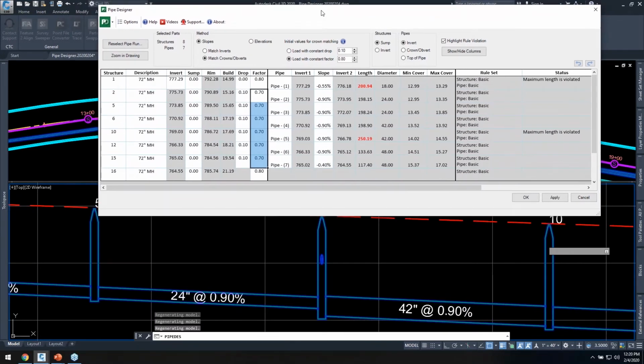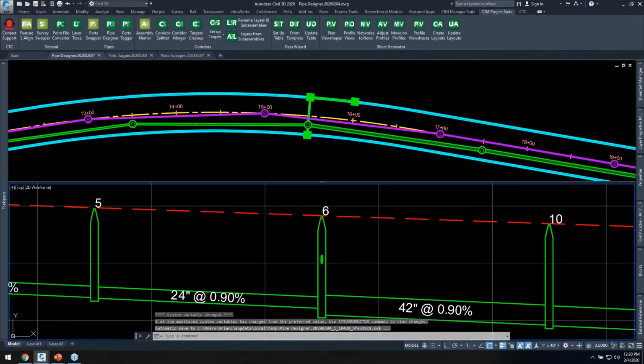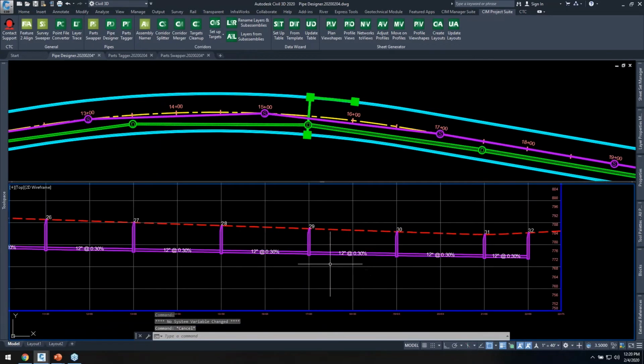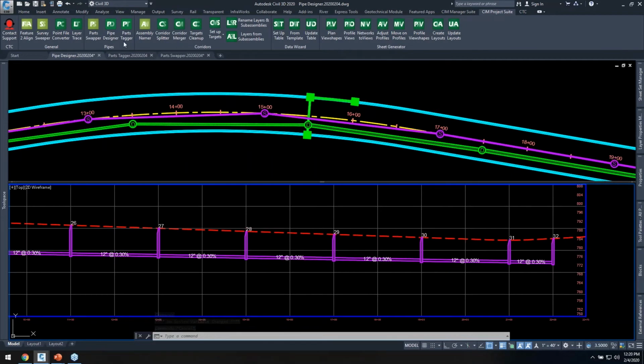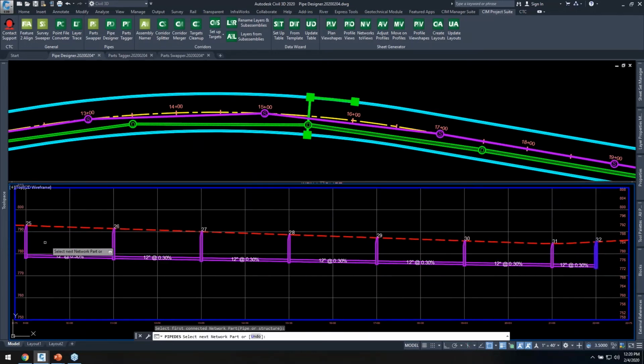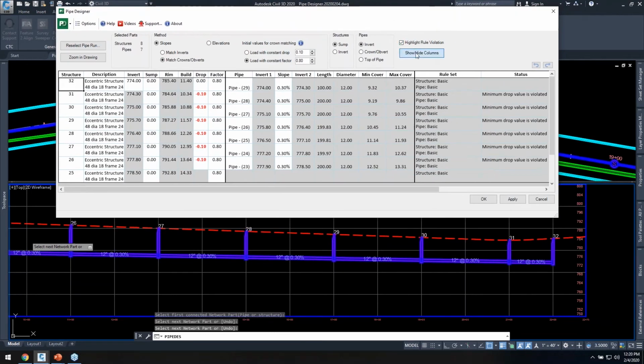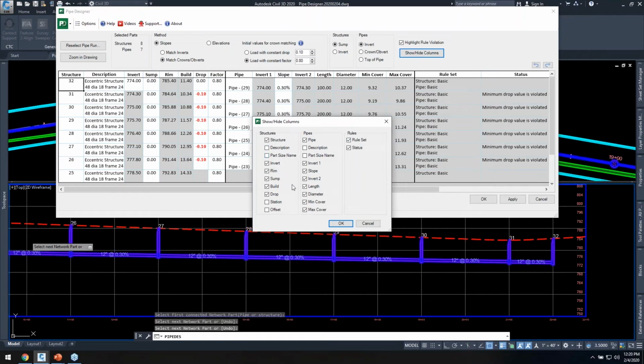So what about a few other scenarios? That was kind of a storm design scenario. For working with sanitary, I'd shown you this earlier, we can pick in either direction. So often in sanitary, we might be designing from a low invert, designing upstream. So I could grab this and grab my entire sanitary pipe run. Again, we've got controls on what values are showing here.